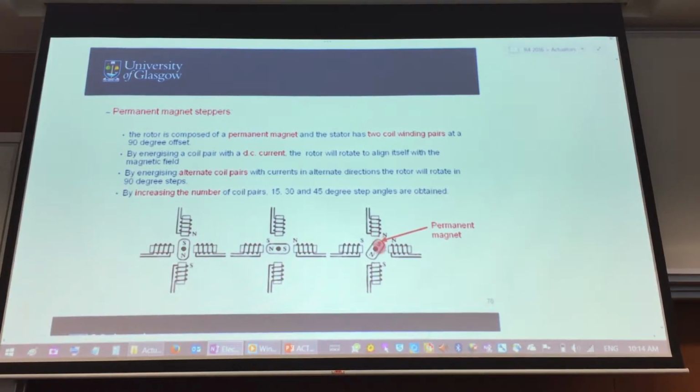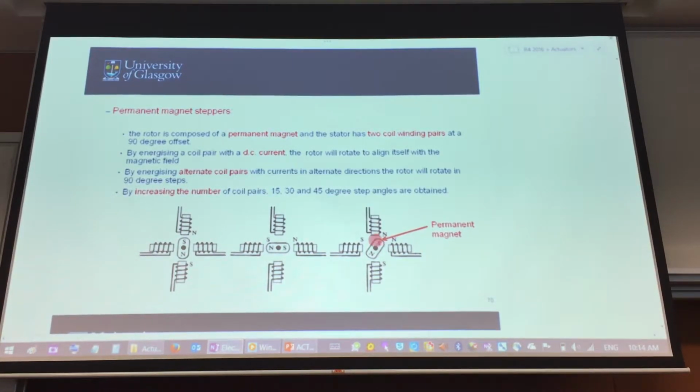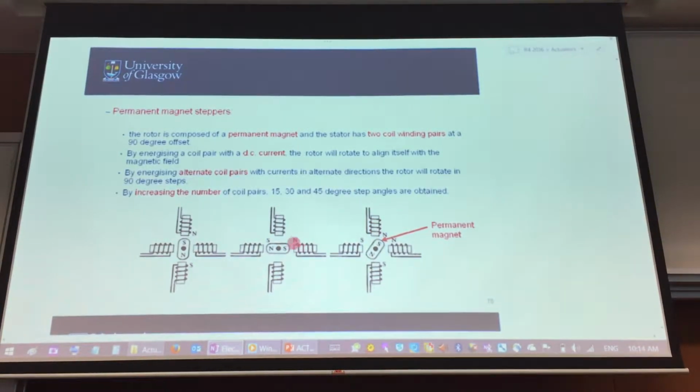So in that case, your south pole will move kind of like 45 degrees in between. And after that, I'll de-energize this north pole at the top, and then maintain my north pole at the one on the right. So you can see that sequentially, this core is going to rotate continuously. Those are the things that can be done to move that magnetic rotor,